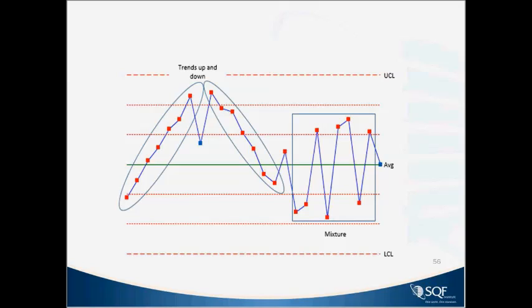Should alert you to the fact that, hey, you shouldn't have that many points out there in that zone. Most of them, again, we said 68% of our points should be within the first zone from that mean. So that tells, again, the operator that something's going a little funny in the process and that you want to be alerted to that. So keeping an eye out for that.